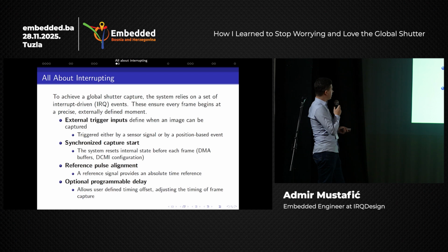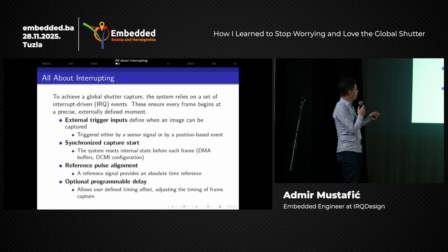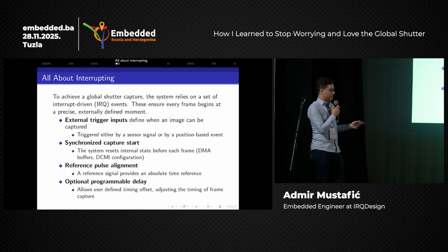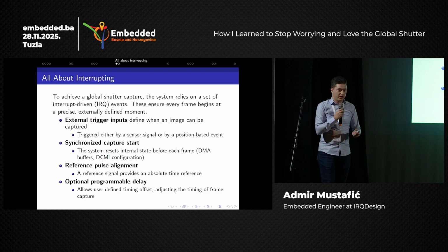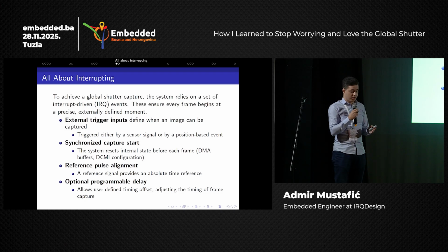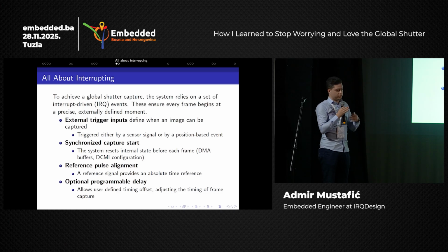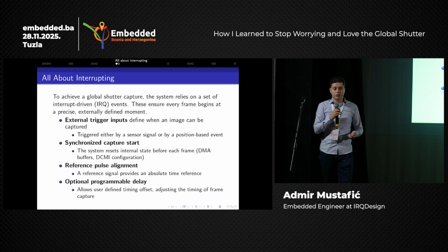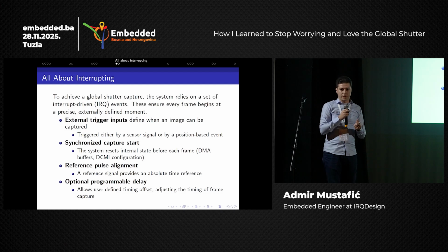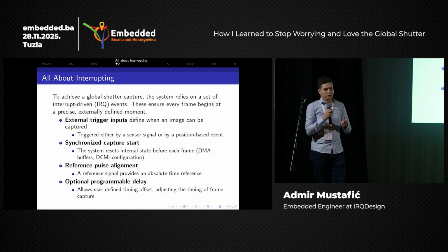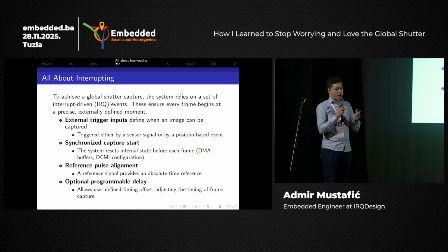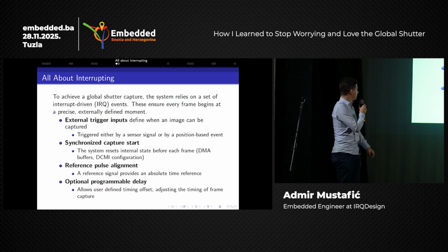To ensure this, as mentioned, we have the external trigger inputs, which can be just a periodic pulse train, the sensing image, or the sensor from the conveyor belt itself, the frame rate or the revolutions, and in the form of an encoder where the user can also define the offset of the capture itself in pulses or in time itself, for example, in microseconds.